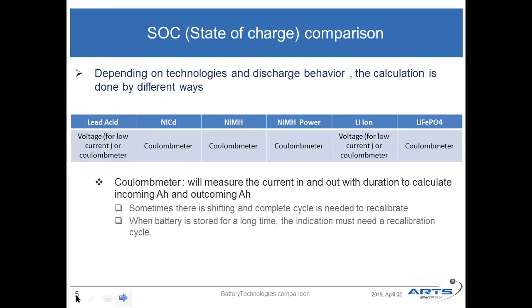Now, on some applications, very often customers are looking for the state of charge of the product. The state of charge can be evaluated in two ways. The first way is based on the voltage value during the discharge. This is mainly used when the current is quite low and stable. That means the discharge curve can be used all along the discharge, and so we can have a correspondence between the voltage and the state of charge. This is the case for lithium-ion products and for lead-acid products.